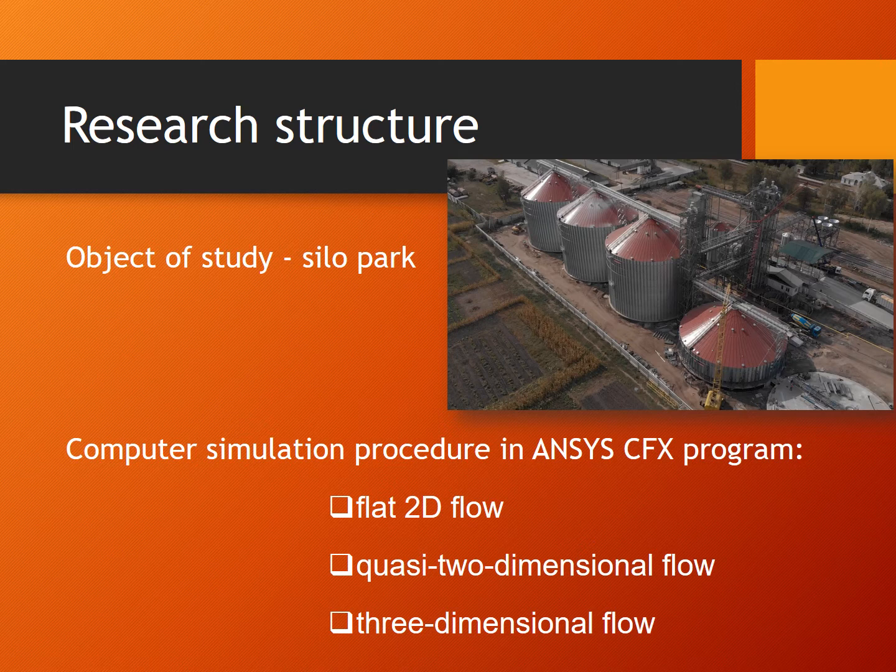This article presents a computer simulation procedure in Ansys CFX program for flow around the models of various cylinder configurations that schematize a silo pack. Analyzed silos, the size of which are most often built, are from 11 meters to 30 meters. The roughness of the silo surface was taken equal to the height of the corrugation of the silo body.